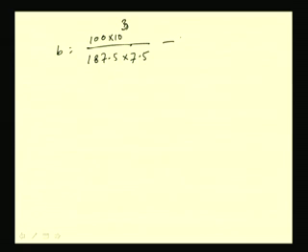So all these values, if we put in this equation, we will get the values. So B will become: R is 100 kilonewton, that means 100 into 10 cube, by sigma P is 187.5 as we have calculated, and thickness is 7.5, sigma P into t minus root 3 into H2, H2 is 29.25. So after calculating this, we will get 20.45 millimeter.